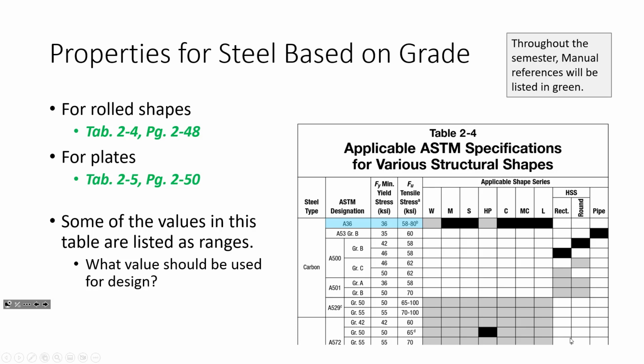The range is there to inform you indirectly of a material's ductility, okay? So what you will find when you produce steel is that, as you're producing it, you do quality testing on heats of steel as the steel is being produced. You do a stress strain test on given steel coupons, and you're going to find differences in variability in tensile strength. Okay, what you find in steel is that as the tensile strength goes up, the ductility goes down.